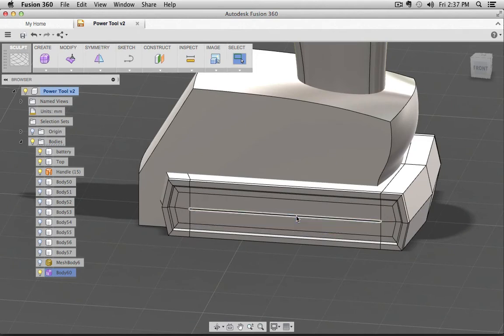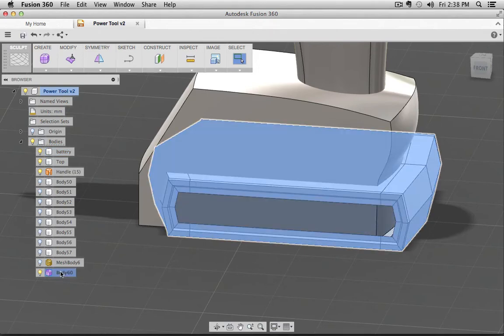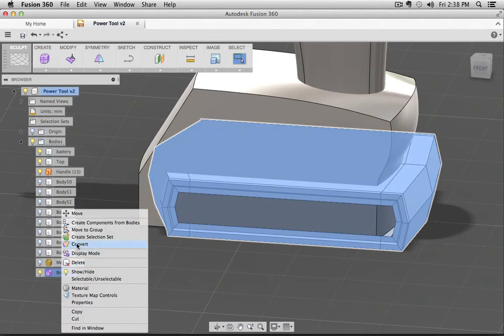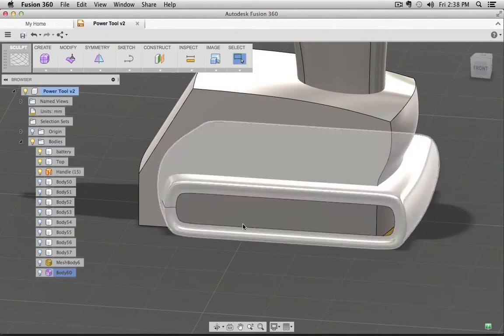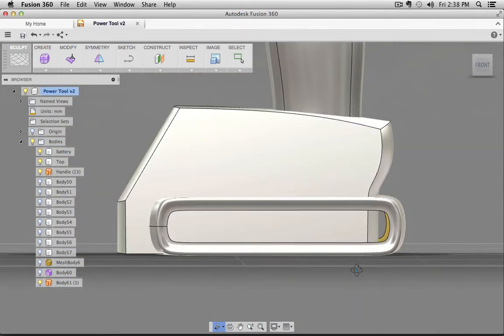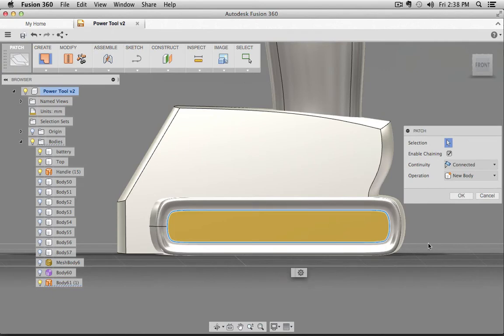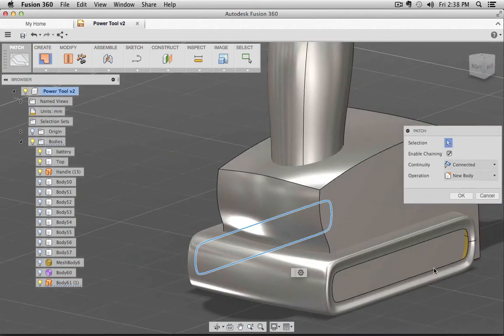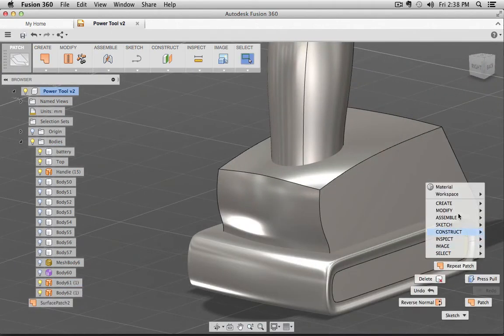But what I would like to show you is, this is one way, for example, how you can do this. So I go ahead and mesh model everything. I can also take this T-spline object and convert it into a B-rep. So I have this open gap. So you see, I can see through. But then I can go to the patch model mode and simply patch those openings in.